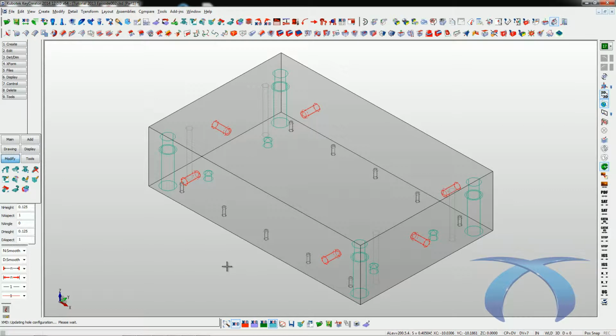And then we have several things that we can do to continue our XMD job. One option is to trim that solid to a trim sheet. So we can trim it to a trim sheet that represents the parting line and the core part data, and we'd have our core block done. So we do have the ability to model it right in here, or we have the ability to bring in a model from another system or another Key Creator user, any way that we feel works best for us. We can bring that model in and work with it. It doesn't matter what software that model comes from, it will work exactly the same.